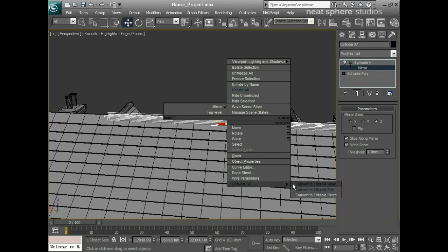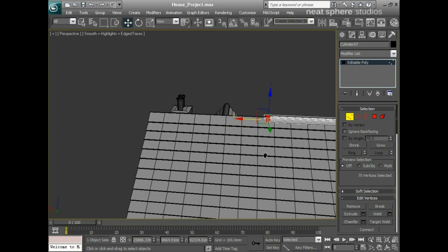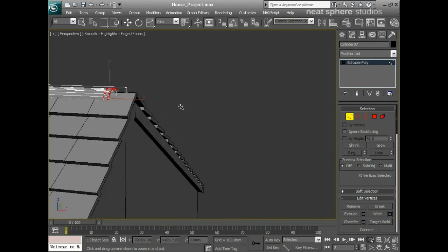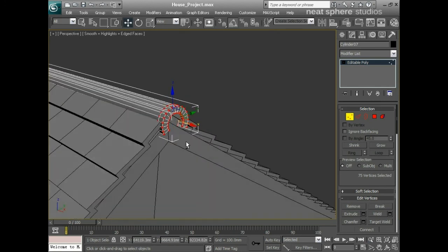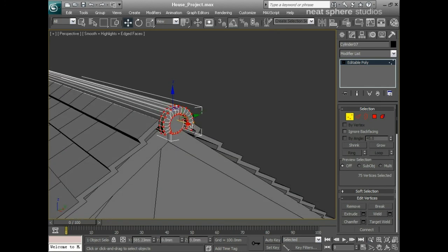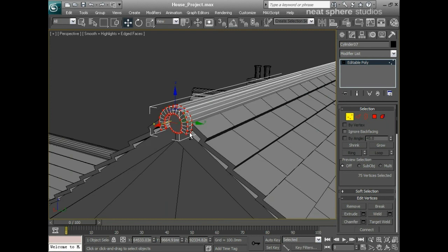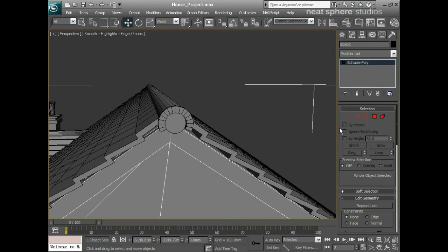And then I'll right click and convert that to an edit polygon. And all I'll do is take these vertices and pull them out to the end. So notice as well, I'm constantly looking and evaluating and moving around the object. There we go, so I'll select this.